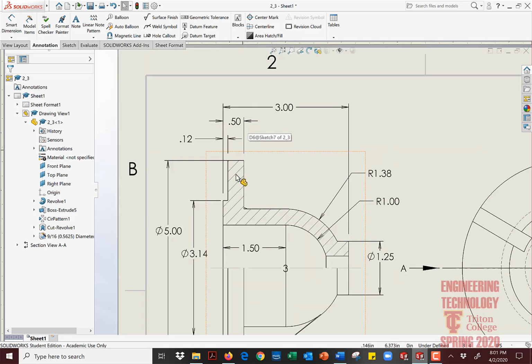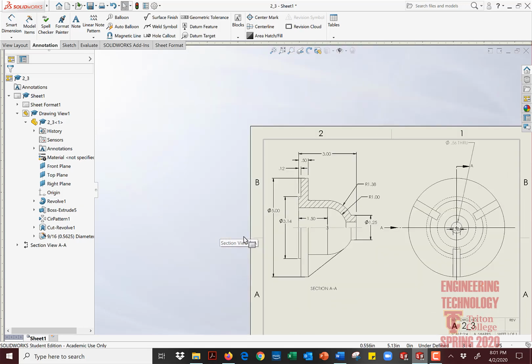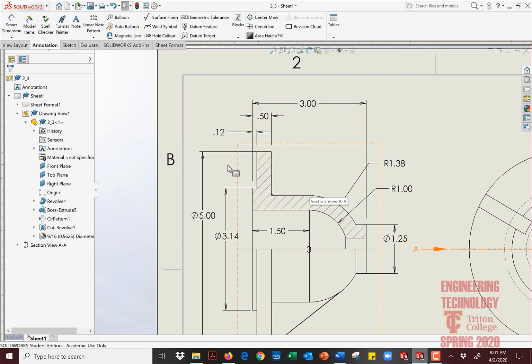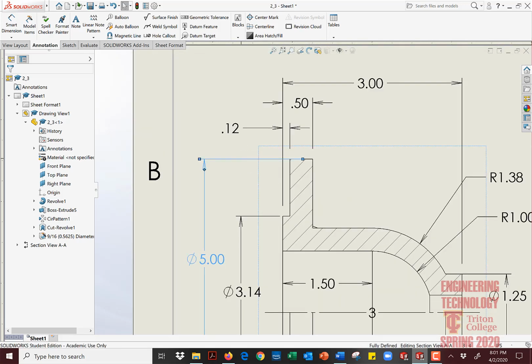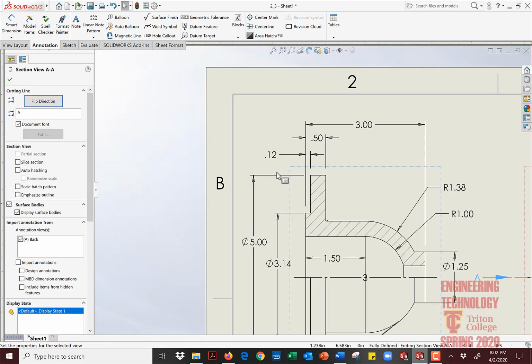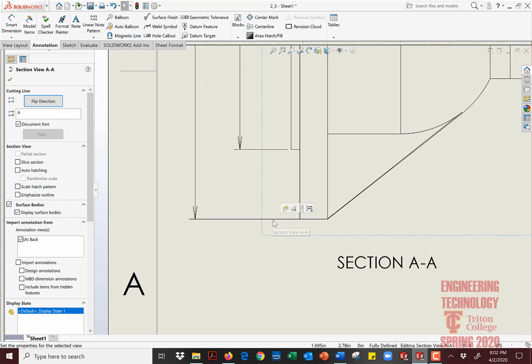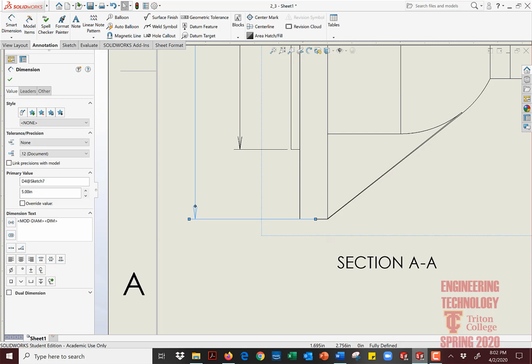So now we've got the open arrows, we've got the nice gaps. Then you start cleaning up your drawing. Because is this right? Now, if you click on this, you're going to find out that the dimensions inside the part, you actually have to drag it out to the tip. Sometimes you got to drag it all the way out and then drag that little button back in. There you go. To make it snap to the right spot. Click this one. You don't want your dimension inside your part. You want it to the corner of it.